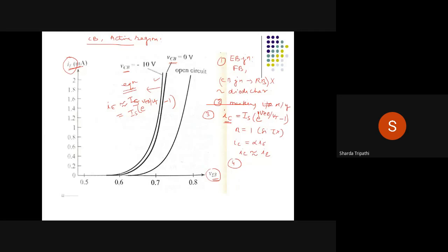And IC is at the second PN junction which actually is reverse biased. So there were two currents there, one was the reverse saturation current and the other was the current coming from the emitter, right? We saw that IC was equal to alpha times IE plus ICO. So this ICO is the reverse saturation current. That's why I just wrote this as IS. Okay.